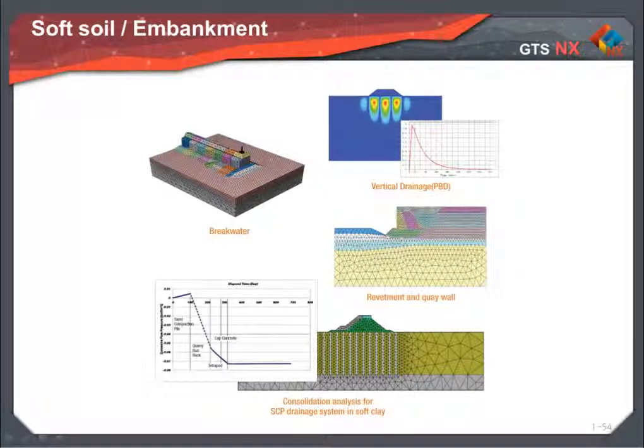When we deal with soft soil or embankment, we can calculate the dissipation of generated excess pore water pressure in the model due to the surcharge loading process. We can extract graph representation of results for time settlement behavior of various types of surface profiles. Or we can look at the acceleration of soil consolidation using vertical drains in 2D or 3D.